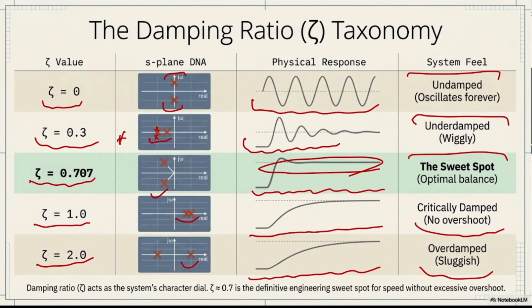It is going to act based on its instincts, based on the place of the poles. Still, it's not that bad, but also it's not that good. That's why I would like to emphasize that every time you build a system, or at least try to design a system, you have to make sure that all of the poles are going to be on the left side, despite the fact that they have imaginary or real parts, or both of them at the same time.